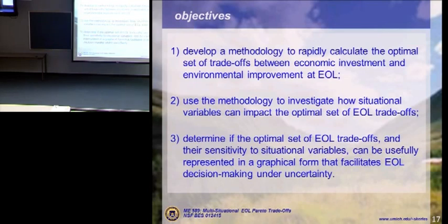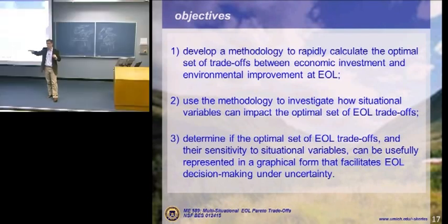Let's suppose that we're looking at energy recovery and cost at end of life. If I have 100 kilojoules I'm getting back from the product, and that cost me 50 cents, and that point is on the Pareto set, it means you can't recover that much energy cheaper. It's just the best trade-off you can make between energy and cost. What this methodology does is establish that front. And in doing so, cleverly using genetic algorithms, you can get that front established fairly quickly, which allows you to do extensive sensitivity analysis. I'll show you what the results look like a little bit later.